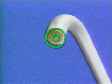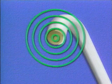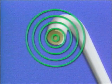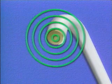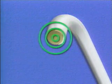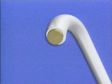Whenever there's a change in current, the magnetic field also changes. The voltage that's induced in the conductor is always in the direction that opposes the change in current. In other words, if the current is trying to increase, the induced voltage opposes the applied voltage and opposes the change in current. If current is trying to decrease, the induced voltage aids the applied voltage and opposes the change in current.